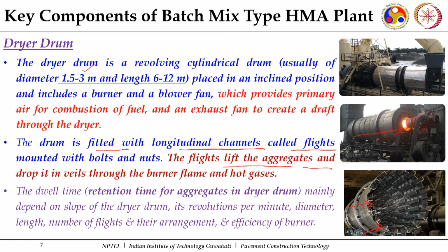So, it is very important to look into the dwell time, especially the time for which the aggregates remain in the dry drum, because that will help us attain the temperature which is required for mixing these aggregates with the standard grade of binder.